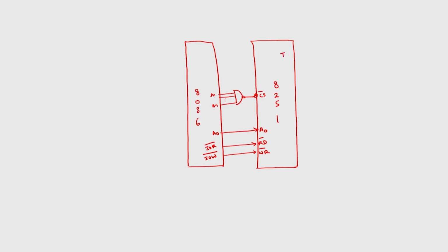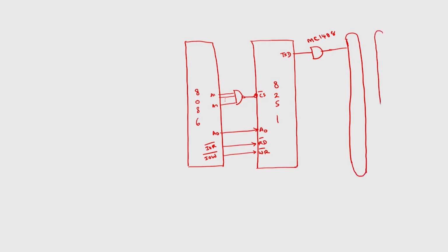Then the transmit data pin will be connected through MC1488 to the RS232 interface. This is transmit, and this will be connected to the CRT terminal.